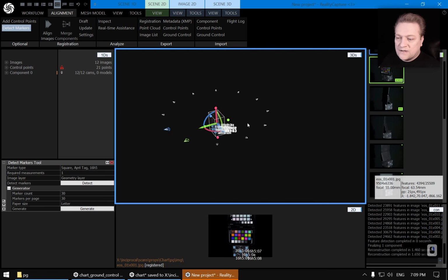And you would see when you run these things that sometimes even without changing anything, you run it a second time, you would get a different result. The reason is that a lot of these algorithms in photogrammetry and optimization in general use some random seeds, and in other cases, especially when it runs on GPU, you cannot guarantee that things are always the same.